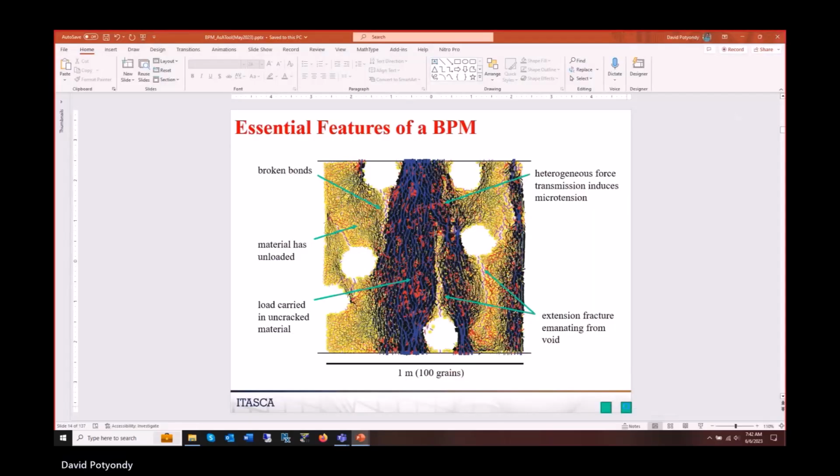So that's the cracking, and this is the same system. And so thickness is magnitude, so you can see it's elastic still. Everything is just getting thicker and thicker, higher loads. Here's the compression getting transferred through the system. You can see the black and the blue predominantly. You can clearly see the tensile load that's developing above and below each hole. There's the stress strain curve.